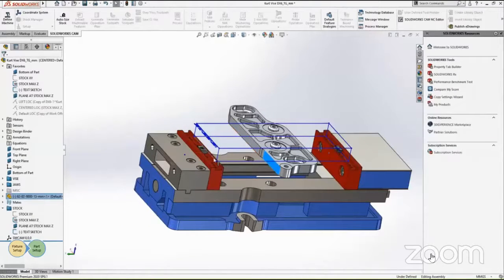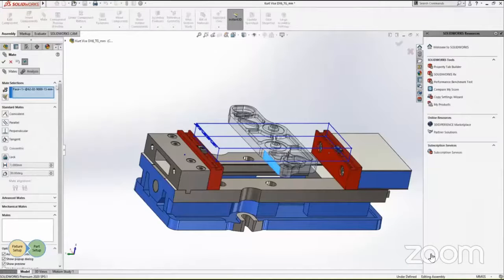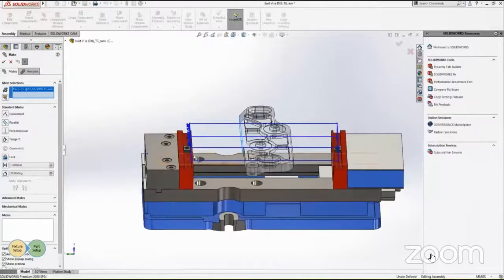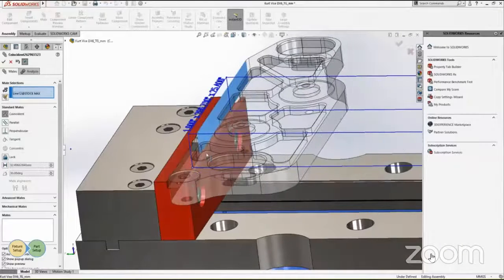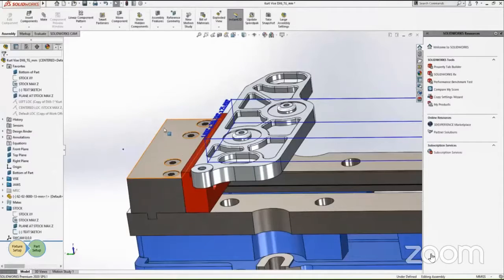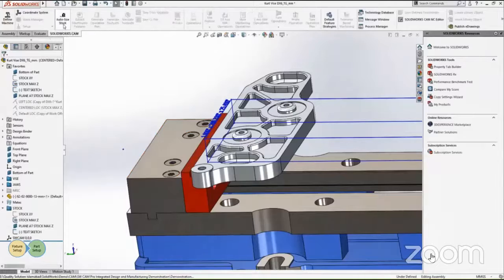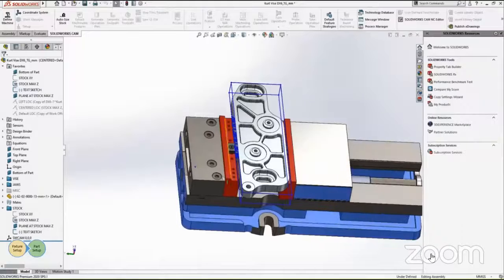All right, we can perform the constraint so that the front face of the CAD file must be parallel to the sketch line. So we go to the assembly, select the mate, and click the front face, and then we will click the line of the sketch so that the front face is coincident with the line, and it is also parallel along the line. All right, so this orientation is much better. We will press the auto size stock. It will again resize the 3D sketch of this stock.